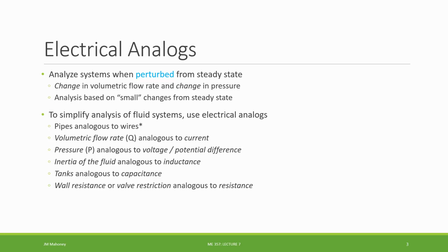The inertia of the fluid is going to be analogous to our inductance. We're going to see that by the impedance values we find for fluid inertia matching those we see in inductance, where it's going to be our current, or in this case our flow rate, times an S term times a constant.